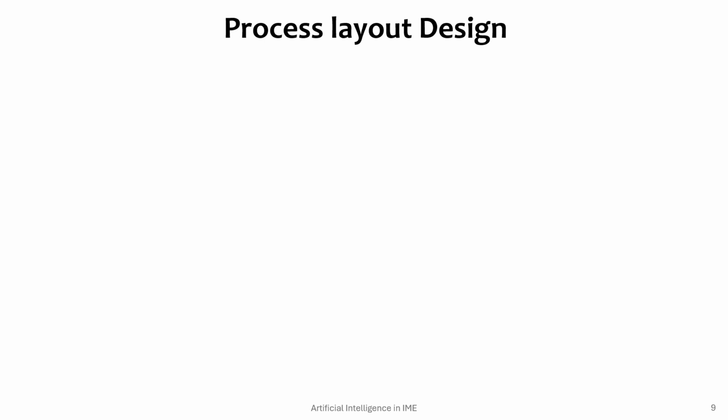We are talking about designing the process layouts. So let us continue from the last lecture. While designing these process layouts, what we have with us is the historical data. Let's say you are in the business of developing customized products and you have a workshop. If you are tracking the interdepartment movements or the transfer of materials or workers from one department to another, then you can utilize this kind of quantitative data to develop an efficient space layout for your process layouts.